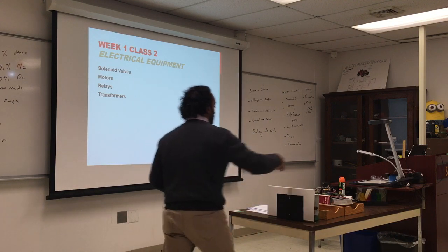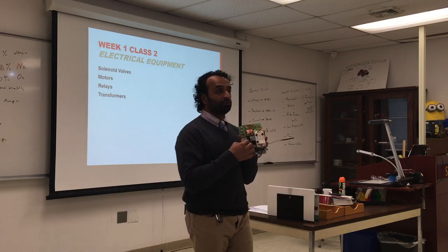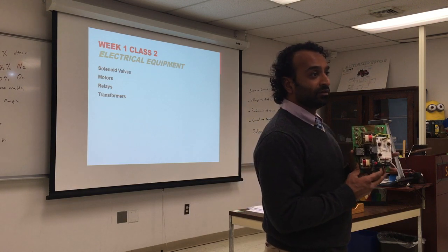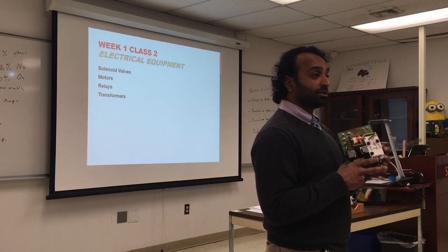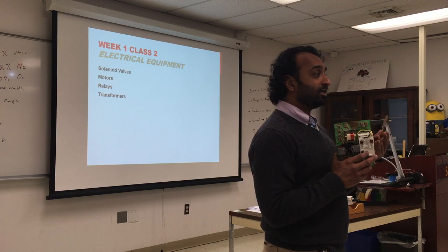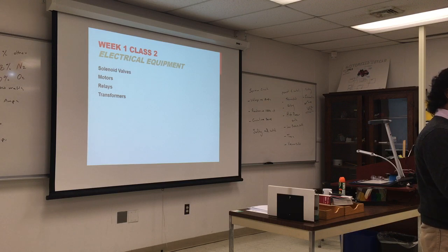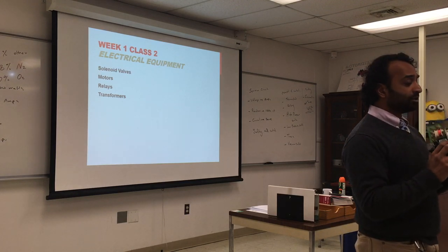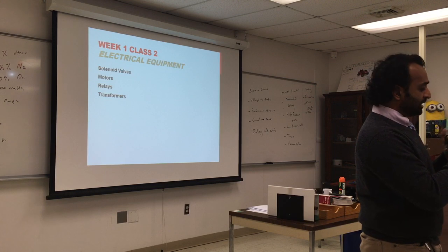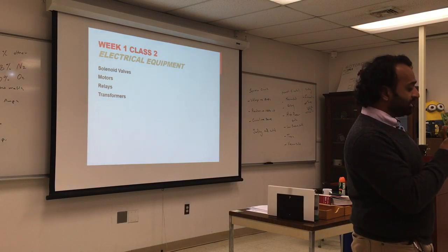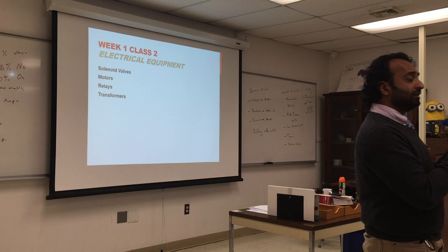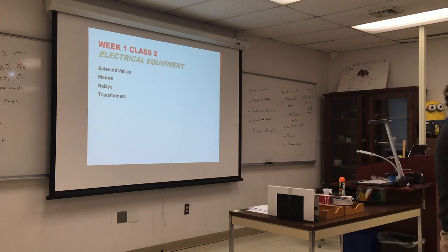So relays control things. If we look here, we have two relays. One of them will engage. The relay has an input, right? This is the sensor, which is inside the tank. It senses the temperature. Once the temperature is within those two limits, it will close the circuit and engage this relay. This relay will tell the connection here for the burner to turn on or off. So the relay has an input and closes a circuit.